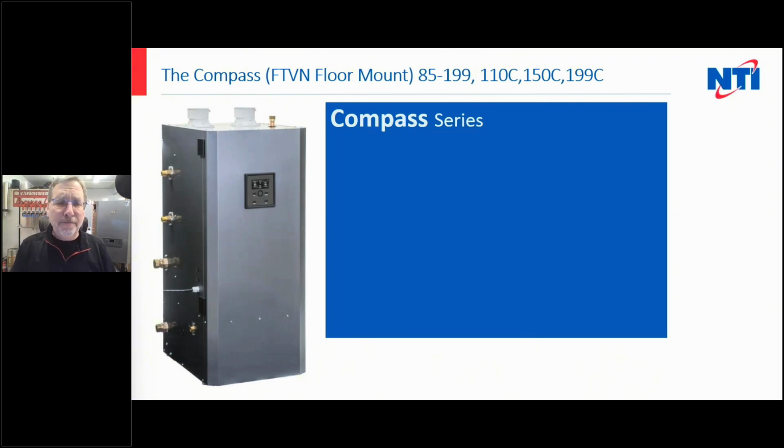In my son's house, which was all cast iron radiators and all cast iron baseboard and all steel pipe except for about 40 feet of copper inside the actual boiler room, I remediated the water. I put Fernox number 3 through it and cleaned the system up and flushed it. And then after I put the new boiler in and filled it, I put Fernox number 1 in it. And I put a low loss header with a magnetic separator built in, a SEP4, I think they call that. And so I remediated the water, and now 7 years later, that water is still perfectly clean and still tests neutral on the pH.